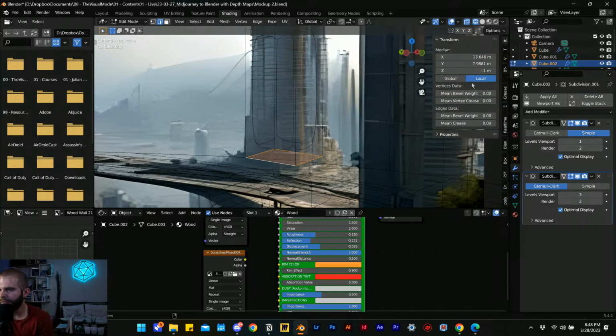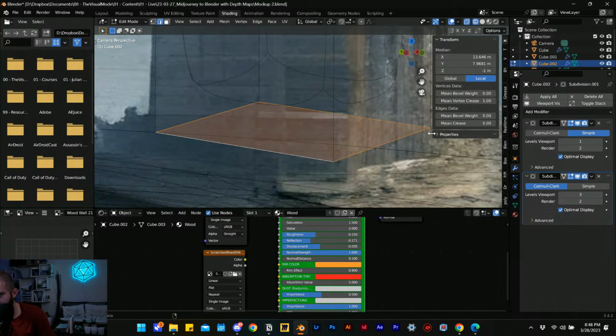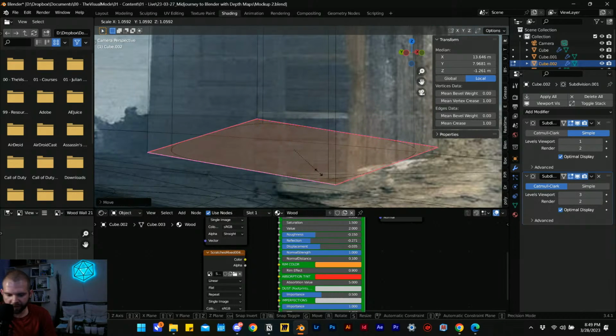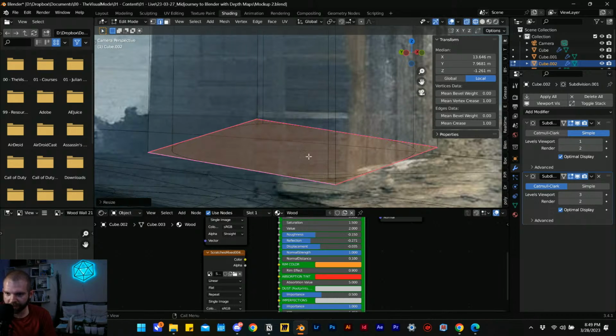And if we hit N, we get different properties here. So at the very top for the item, we can see we have a bevel. So we can set up, not a bevel, crease right under it here. So we can take this value up and create a clean crease. There we go. If I zoom in right here and I increase the edge data for the crease, it's flattening out at the bottom, right? It goes from this round sort of egg bottom to just a flat. So I could see that I actually want to move all these a little bit lower and scale this up a little bit. Okay.